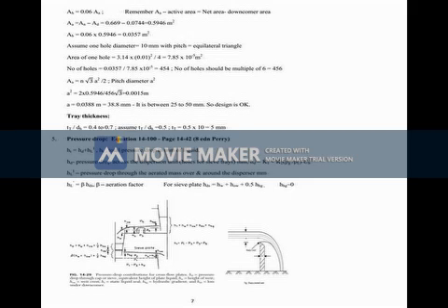After drawing the equilibrium curve, mark the point: take 0.06 on the y-axis and draw a horizontal line to meet the equilibrium line. The xn will lie on this line. We don't know where the actual xn will lie. Then mark A, that is x0, y1. x0 is 0, y1 is equal to 0.00128. This will represent the top of the tower.